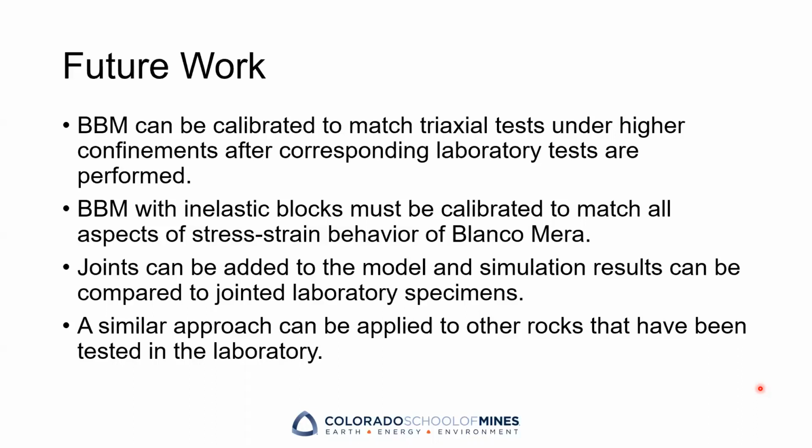Finally, once the BBM is fully calibrated, pre-existing joints can be added to the model and the stress strain behavior can be compared to jointed laboratory specimens. In general, this process can be extrapolated to other rock types, given that laboratory data on stress strain behavior is available. So BBMs can be used in lieu of laboratory tests to acquire data on the stress strain behavior of rock masses. This data can then be used when designing excavations, where an increased knowledge of rock mass behavior will lead to safer and more